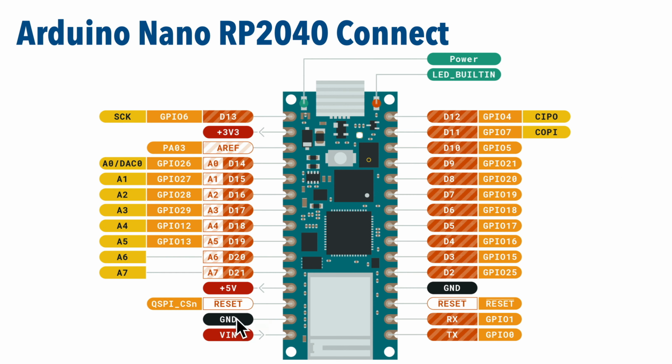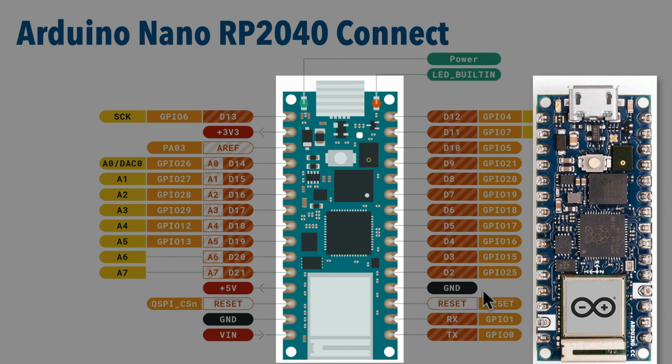the ground pins. Now we almost always use ground pins when connecting devices to our boards. This board has 2 ground pins, either one will work, and one thing that's useful on this particular board, even though the diagram doesn't show you, if you look at the actual board, the ground pins are highlighted in white, so they're easy to find.